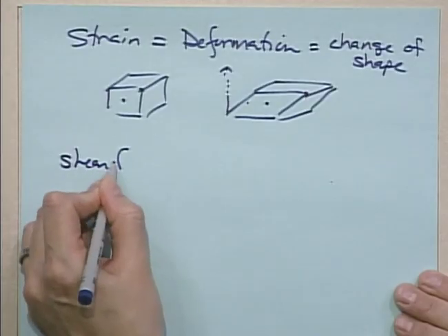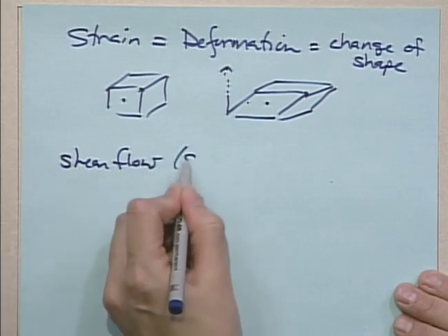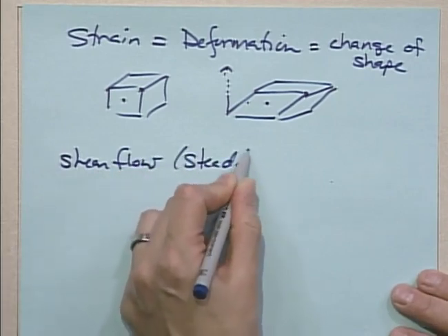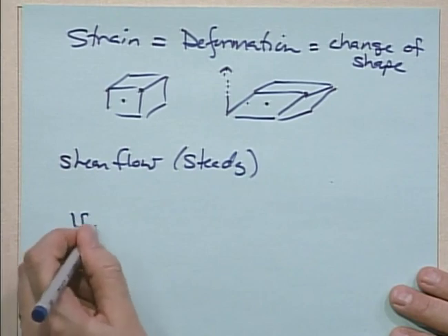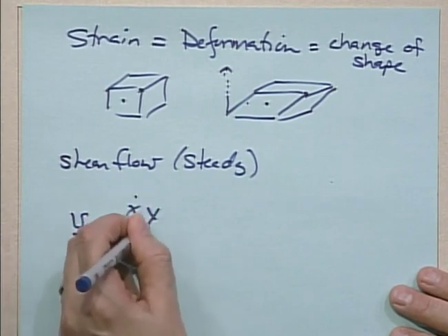So we can get specific about these displacement functions because, as I said again, we know the velocity field for shear flow, and I'm starting with steady shear flow. We know the velocity field: V is equal to gamma dot naught x2, 0, 0.